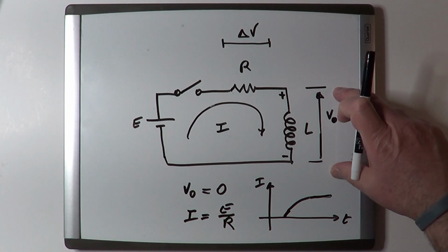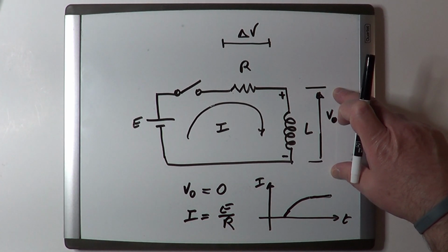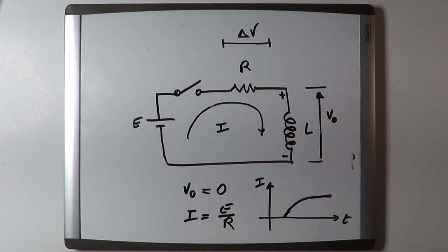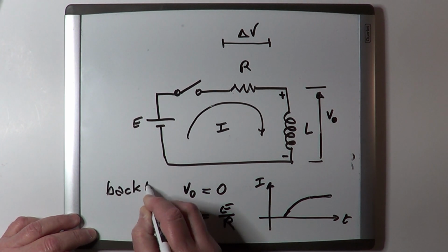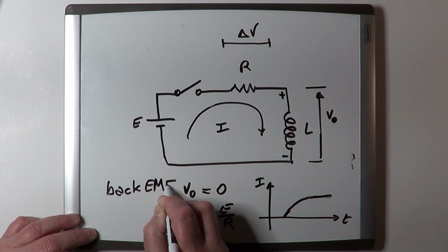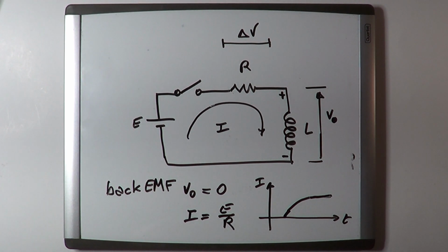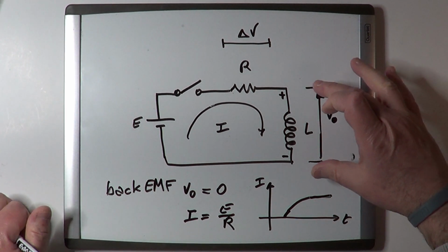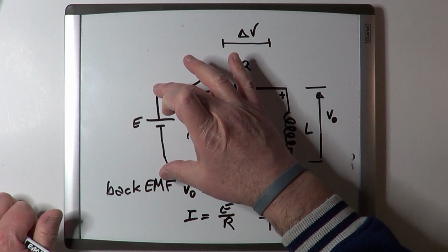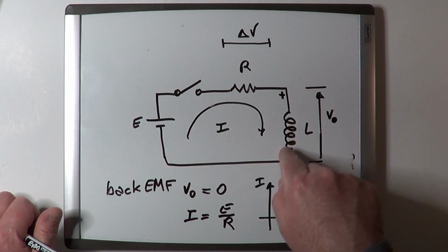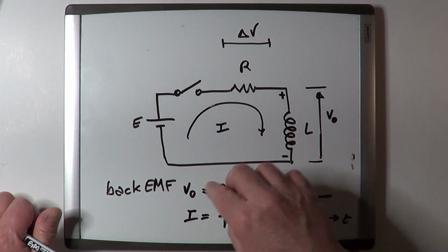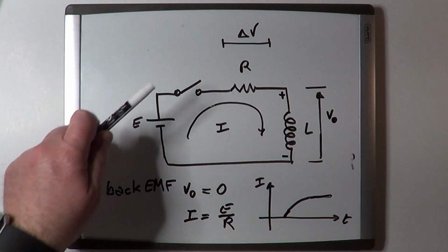The voltage across the inductor L is called counter electromotive force, or back electromotive force, or simply back EMF. Basically, this back voltage is the one that opposes the voltage applied to the circuit by the generator, and then will cause the current limitation, and the current won't be able to flow across the circuit right away when the switch is closed.